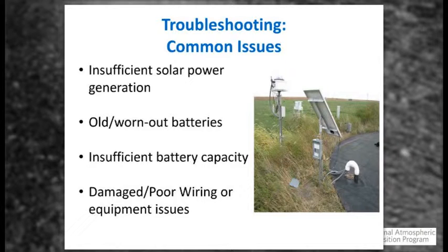As Chris mentioned in one of the other ones, old worn out batteries. It's recommended that every 6 months, I say coming out of winter and before going into winter, you take your batteries and have them load tested. Your system is only going to operate to the capacity of the worst battery within the system. So if you've got, say, 2 good batteries and one that won't pass a load test, that system will run only as well as that worst battery.